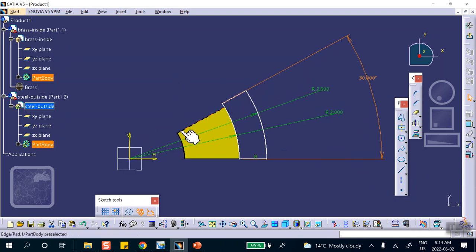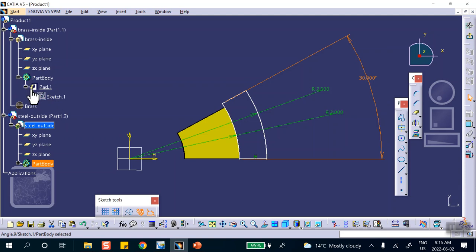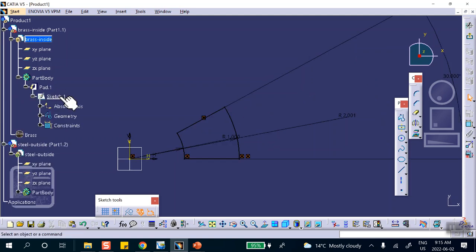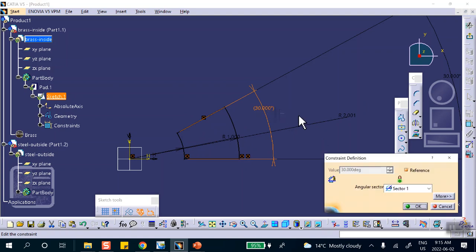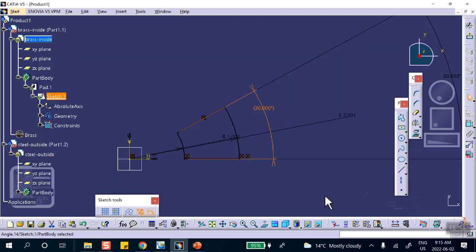Come on. Something weird. So what was this angle? Let's go check that angle. Well, I thought it was 30. I don't know what I put in there, but maybe because of all those changes that I made. Notice that the color, by the way, is not white anymore or green. When you change the color to yellow, this happens. Okay, so let's put an angle constraint between this guy and that guy. Should be 30 degrees. Yeah, it is 30 degrees. Why is it not looking good then?